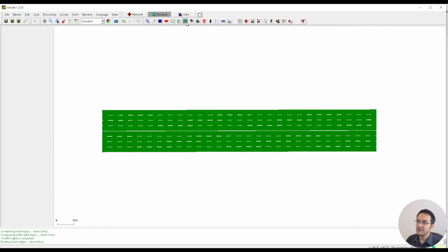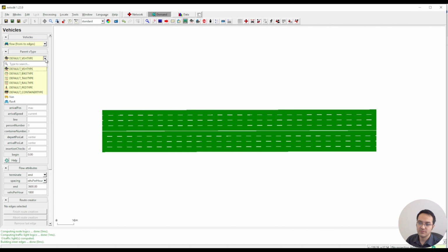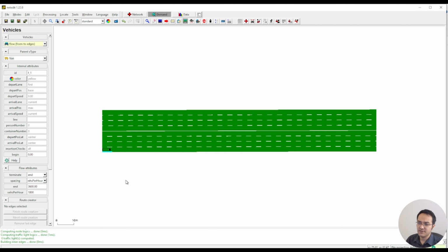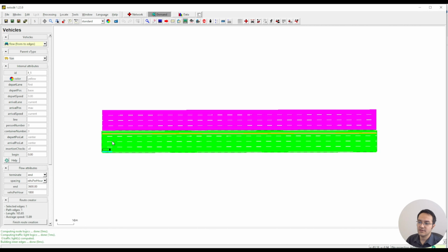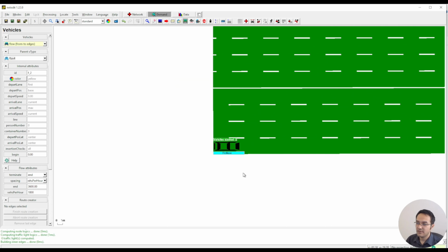Then go to the demand and then the vehicle types, and go to the flow, because we want to add some traffic volumes. There is a van, let's say here, and I'm going to put everything as is, the ID and everything, and then finish for now. There is another one, which is the RAV4, for example. And then the RAV4 is here.